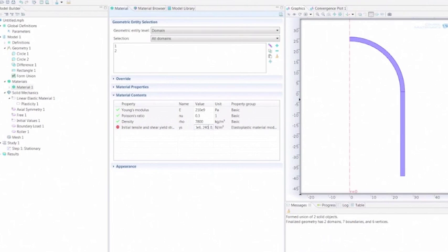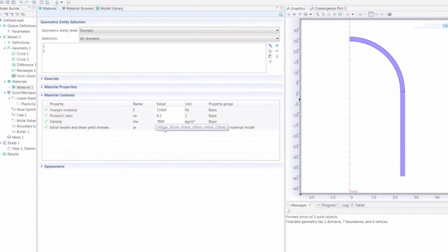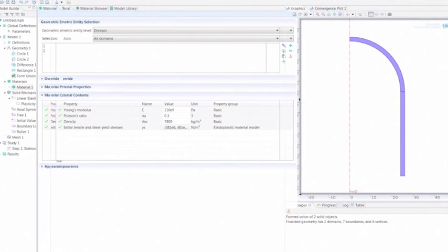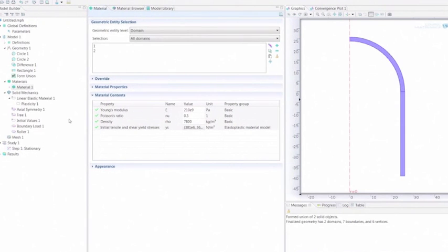And then we have shear, which are 240. This is the direction which is shared with the out of the structure direction. So there are 240. And then the last one is 220. Just to see that everything is correct, E6, E6, E6. That's correct. So the materials are now prescribed.